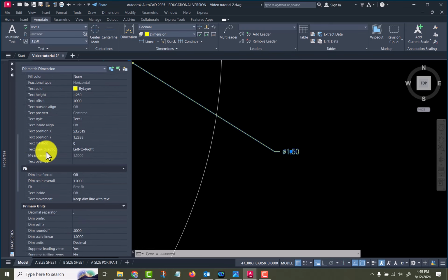And down here in Text, here is one of the examples of where it is permissible to do text override. I've got 4 holes, so I'm going to say 4x and then a space. And I want the original dimension to be used, so I hold down my shift key and put the less than and greater than symbols in there. Another space, and then I'm going to say on a diameter 9.0 bolt center.